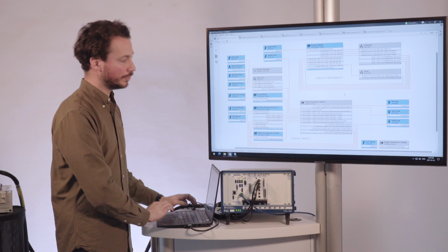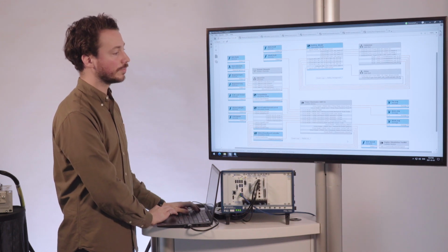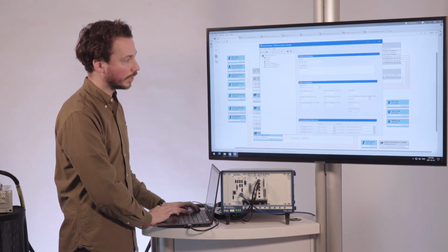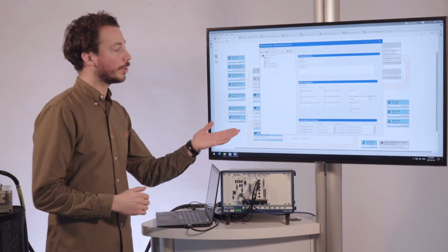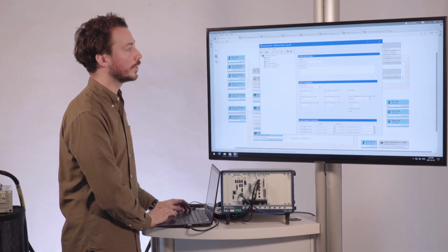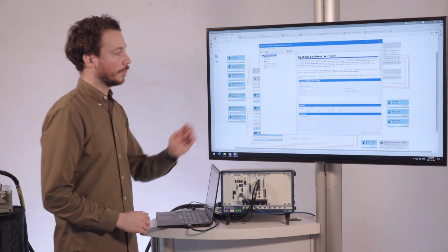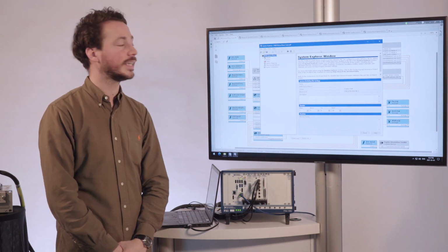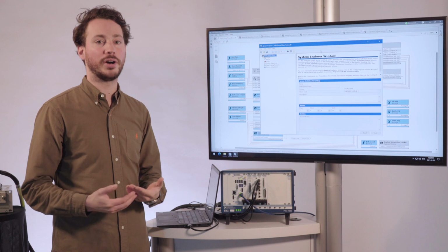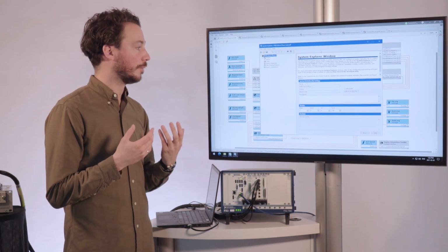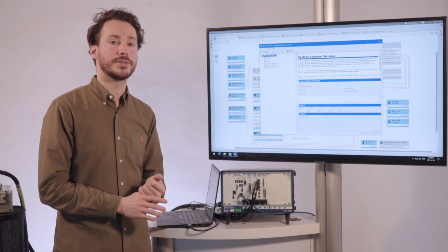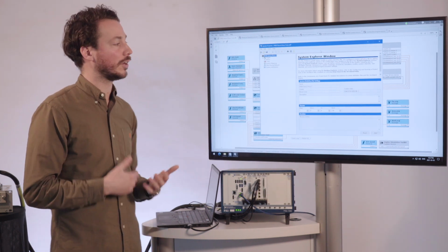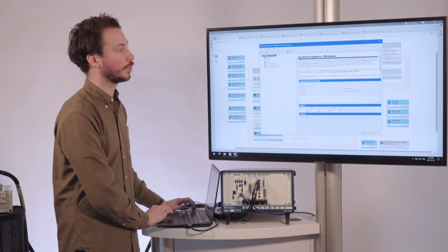The last thing I'd like to show you is the system definition file of VeriStand. So if I open up my system definition file right here, for those of you who don't know, this is what it would look like when you open up the demonstration. What you see right here is the system definition Explorer window of NI VeriStand. And on the left-hand side, we have various parts that we have to actually talk to the model, import models, and configure the whole system. So in other words, this is the main configurator panel that allows us to make sure that all the parts can talk to one another.